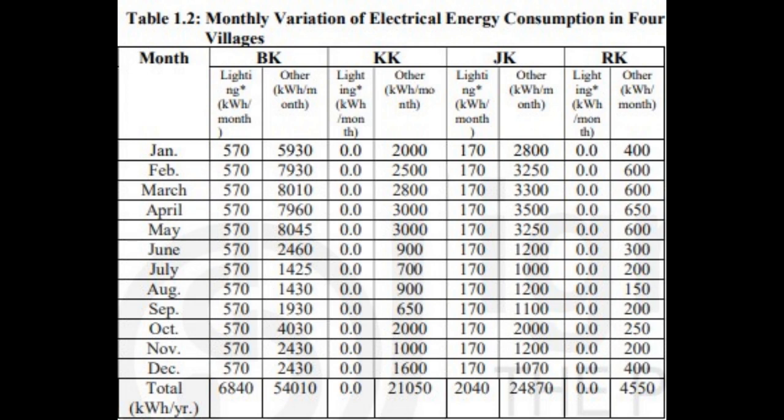The dung thus saved can be used to produce slurry, which will be a valuable fertilizer, and biogas, which can produce electrical power and can be used for cooking, if in excess. The shortfall between the demand of electrical energy and the energy produced by biogas can be met by a photovoltaic generation system and/or a biomass, agricultural waste, gasifier generator system.